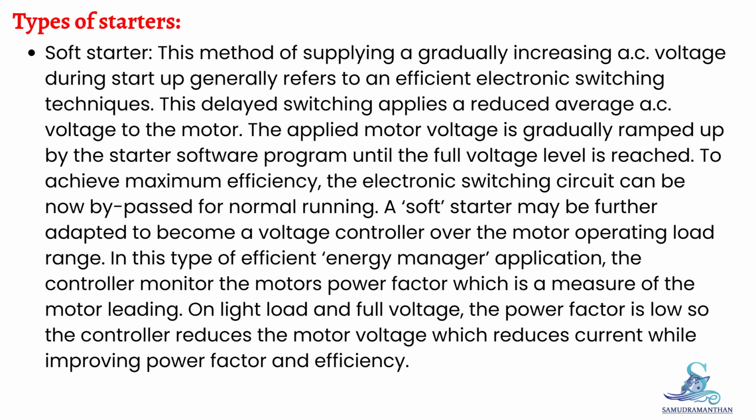Soft starter. This method of supplying a gradually increasing AC voltage during startup generally refers to efficient electronic switching techniques. This delayed switching applies a reduced average AC voltage to the motor. The applied motor voltage is gradually ramped up by the starter software program until the full voltage level is reached. To achieve maximum efficiency, the electronic switching circuit can now be bypassed for normal running.